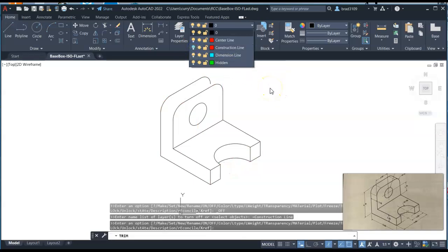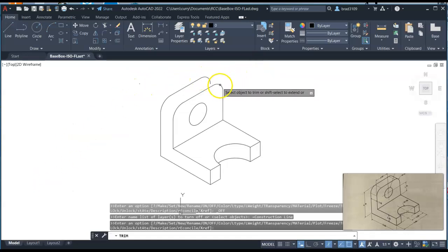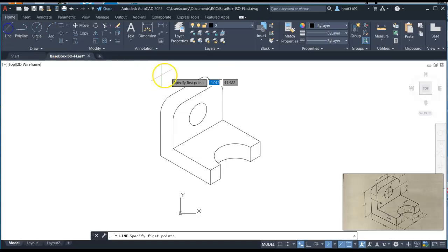Okay. At this point, we have to sit here and think, all right, we've got part of this. Obviously, this isn't enclosed, but what should this look like up in this area, and what should that look like down here so that we can finish this drawing off? We could connect a line from here to there, so let's do that for a second. I could connect the line between those endpoints. But that's not technically correct, because the line that we would see is going to be somewhere back here.